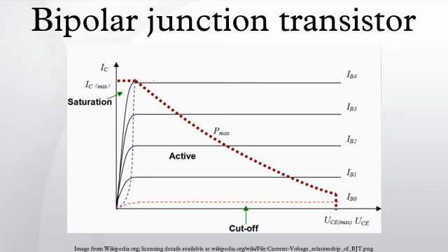It should also be noted that the emitter current is related to VBE exponentially. At room temperature, an increase in VBE by approximately 60 mV increases the emitter current by a factor of 10. Because the base current is approximately proportional to the collector and emitter currents, they vary in the same way.